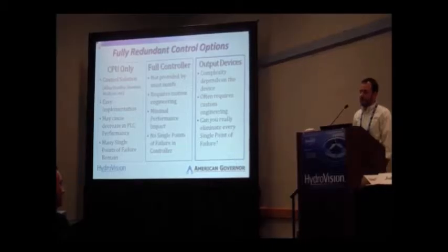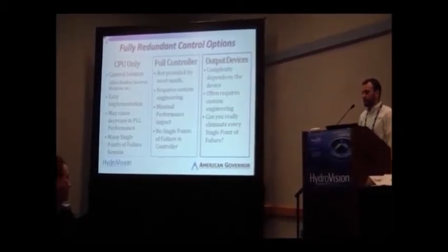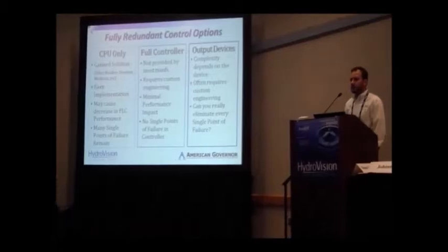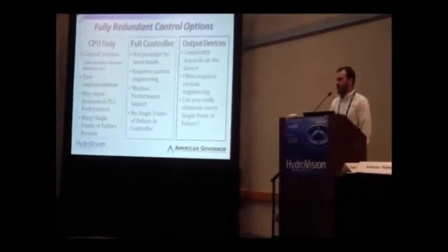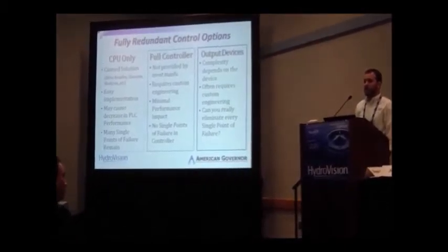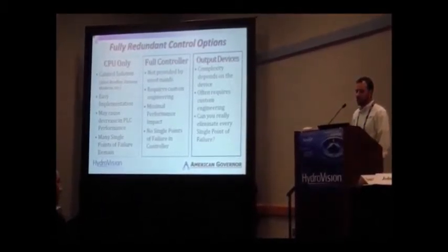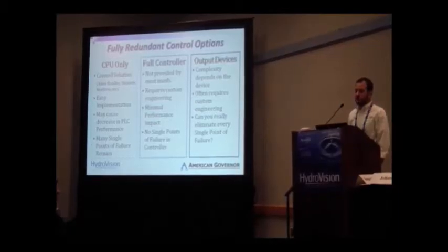And then also, what are your common modes of failure? If you're talking about field devices, say dirty oil going to two valves, maybe having two valves isn't giving you that much bang for your buck anymore. Okay, so when would you want to use these types of systems?